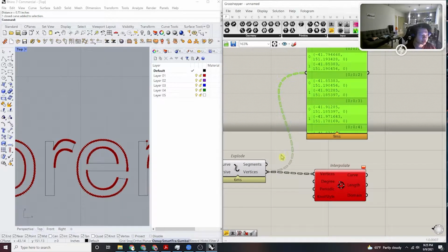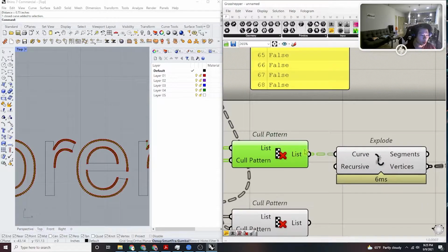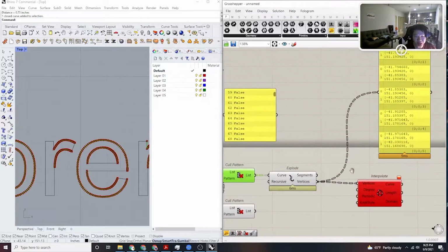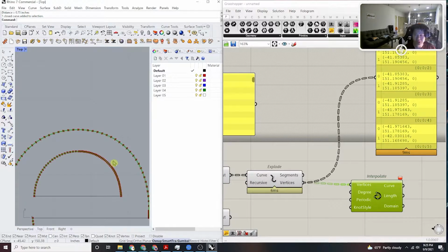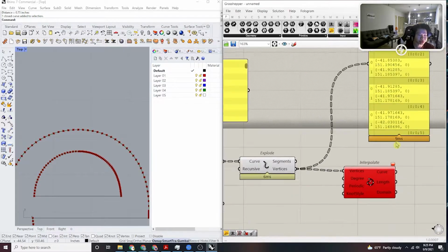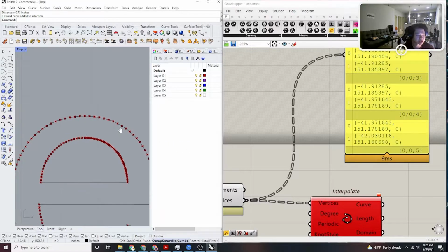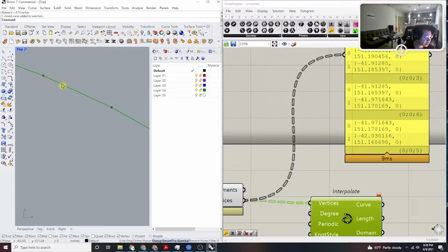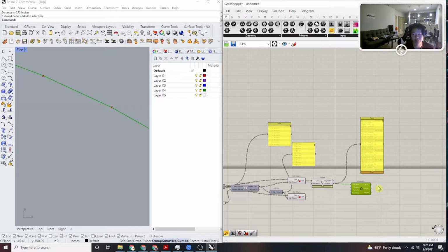Now I'm looking at this, I'm like, okay, this clearly isn't working. So you have to be like, okay, what am I doing wrong here? I ran into this exact same problem. First of all, it's saying insufficient points, but you see it's working here on the screen. So you're thinking, what's going on? It's red. There's a problem here. Insufficient points. Well, basically, it's just making a line. It's just remaking the polyline, which is not what you want. If you highlight this, it's just doing the exact same thing, and that's not what you're trying to do. You're trying to simplify it to make it into control points or something less dense at the very least.